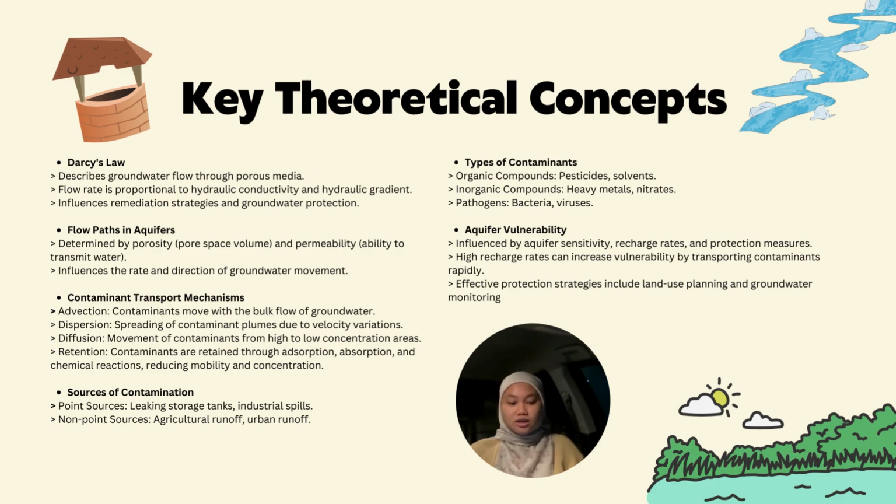Contaminant transport mechanisms, which is advection. Contaminants move with the bulk flow of groundwater. Dispersion, spreading of contaminant plumes due to velocity variation. Diffusion, movement of contaminants from high to low concentration areas. Retention, contaminants are retained through adsorption and chemical reactions, reducing mobility and concentration.